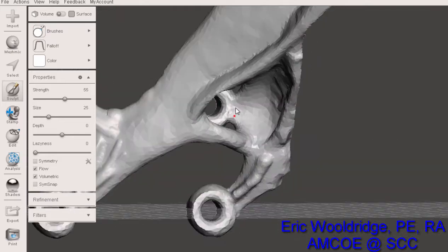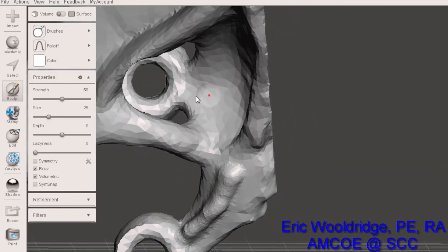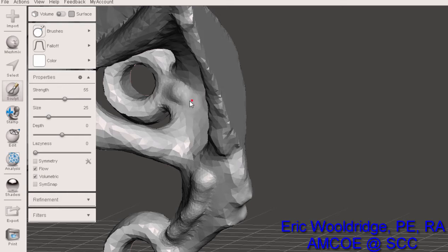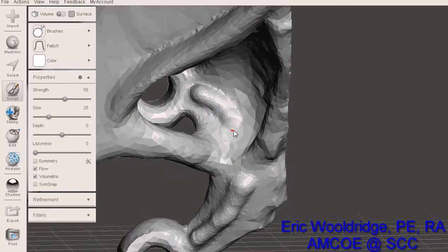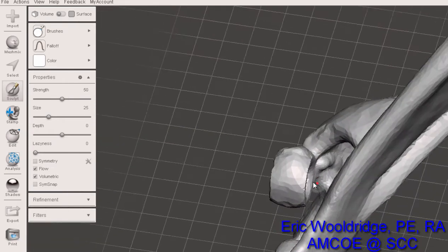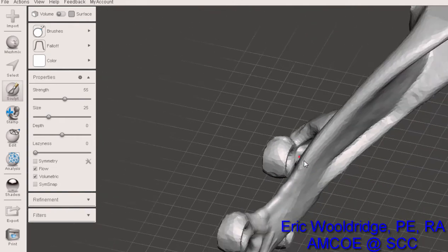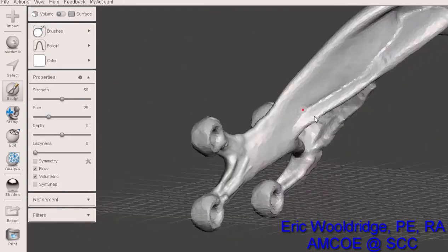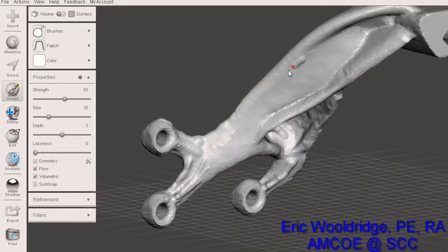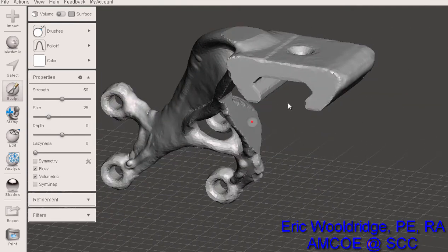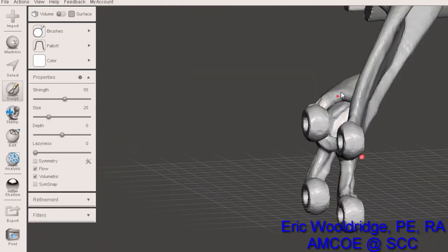We can come check this one. It would need a stiffener ridge on the back side, but you just got to be careful that you don't hit anything. Maybe one on the inside there. We'll take care of what we're needing. Got to be careful though, again, because a bolt is probably going to attach in some of those areas. Okay, so if you see any other areas in the feature, you can always come back through and add more stiffener ridges right along these zones with the bubble smooth or the draw tool, and enhance your part creation and give it that stiffness it needs.